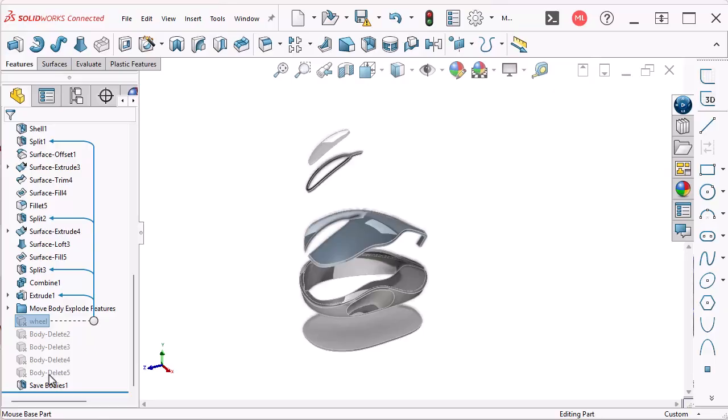And if you don't have one of these reasons for using multi-bodies, maybe you should examine what you're doing and see if it's possibly done better as an assembly. There's always reasons to break the rules and to take little shortcuts, but trying to use multi-body parts instead of assemblies is just a very bad habit to get into.